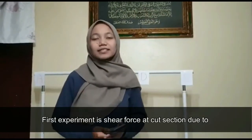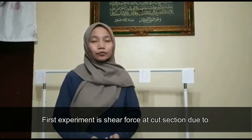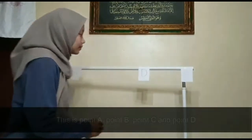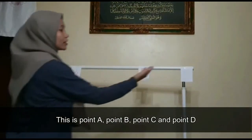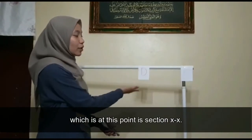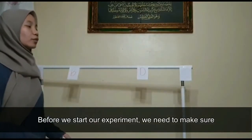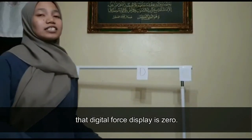The first experiment is shear force at the cut section due to variation of load and variation of load position. This is point A, point B, point C, and point D, which is at this point, this section XX. Before we start our experiment, we need to make sure that the digital force display is 0.